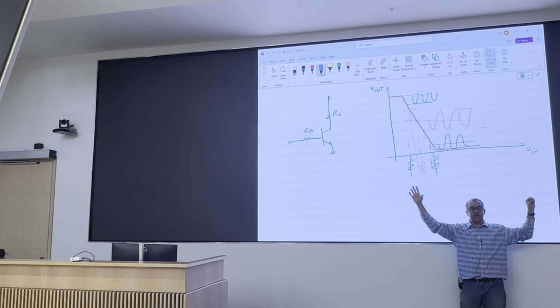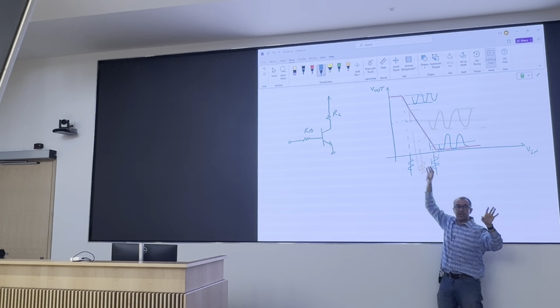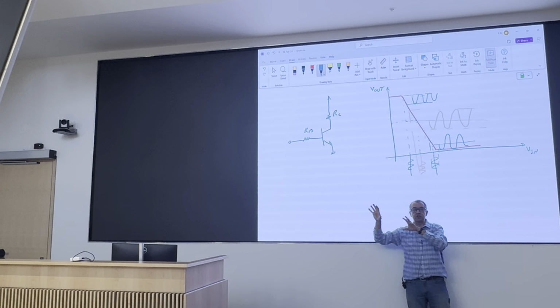So 1 millivolt goes to 10 millivolts after the first, after the second it's 100 millivolts. I would put both of those amplifiers right here, very close to saturation, because I know the signal is not going to be large. But as I get closer and closer to my actuator, in this case the speaker, I want the largest possible signal. So I move my bias point closer to the middle of that curve.